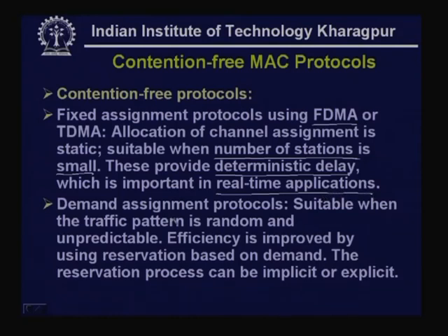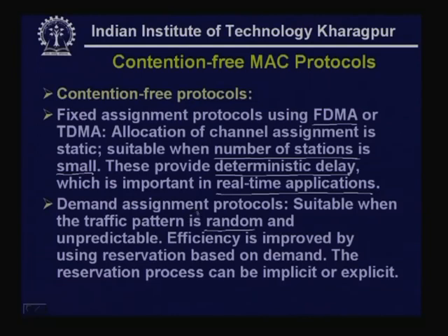On the other hand, demand assignment based protocols, DAMA, are suitable when the traffic pattern is random. That means a particular ground station sends for some time, then waits for quite some time. When the traffic is bursty in nature, in such a case you have to use random assignment based protocols, particularly when the traffic pattern is random and unpredictable. And efficiency is improved by using reservation based on demand.